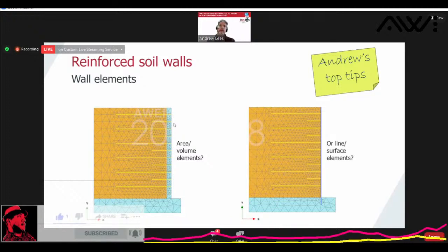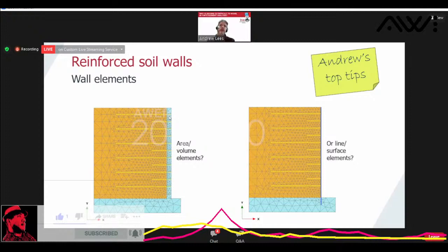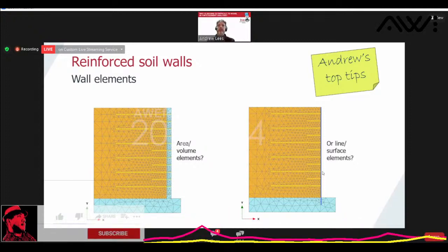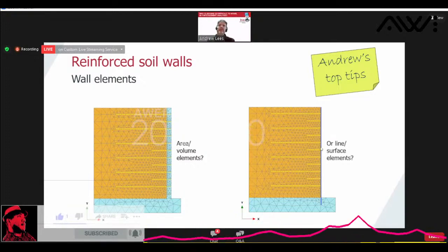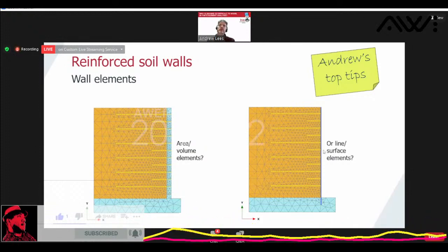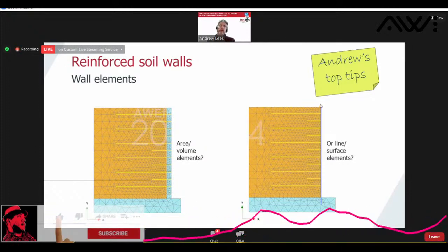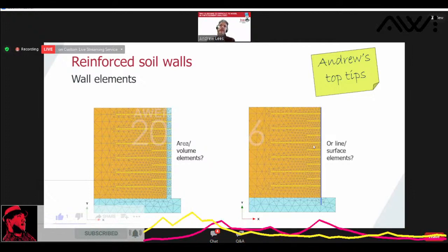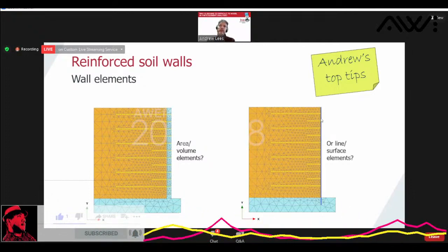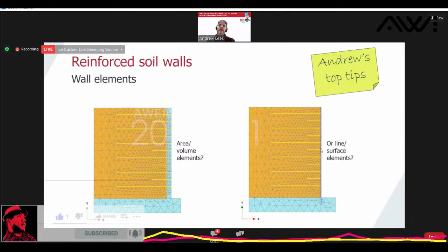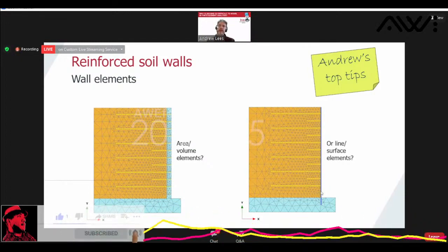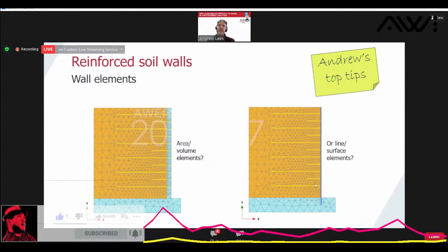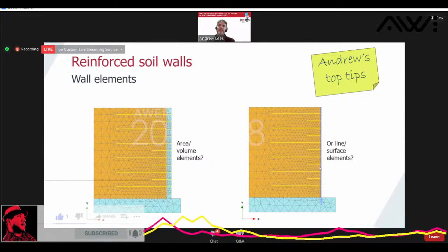So it would normally be conservative, but you've got the joints in the wall facing, which makes it particularly challenging. Walls are made of panels or blocks, so they're not a continuous structural member. You could put hinges in here, but then it'll be too conservative if you do that. It's a bit complicated because normally when the wall is sufficiently high, you've got enough down drag and compression in here that this will act like a continuous member because the whole thing is in vertical compression. But that won't necessarily happen early on.